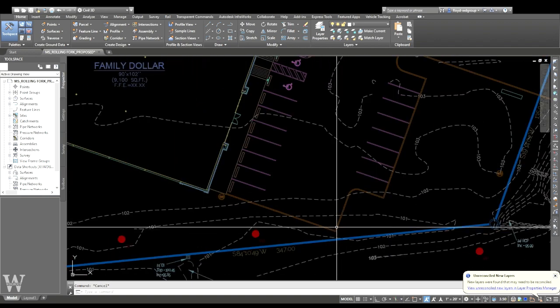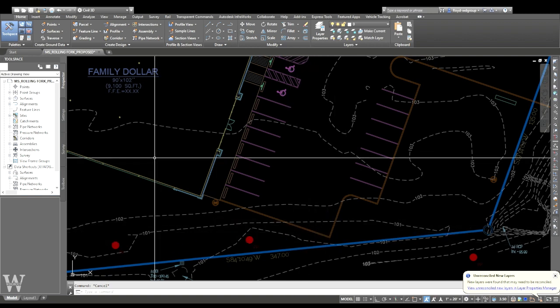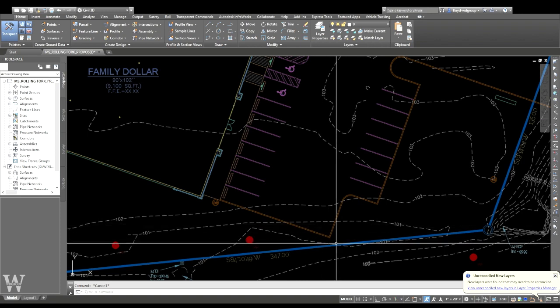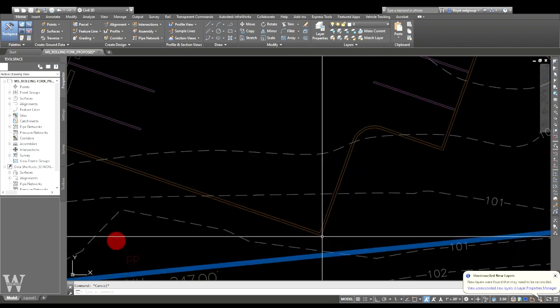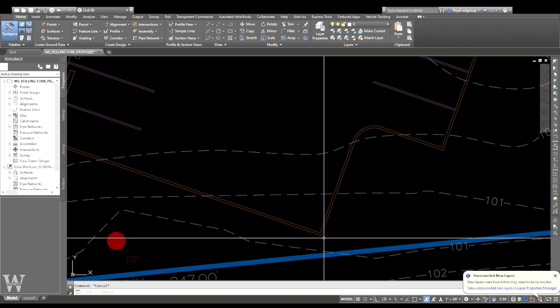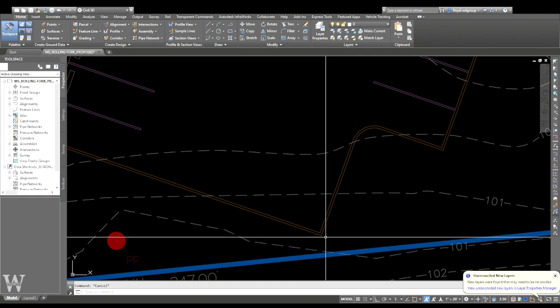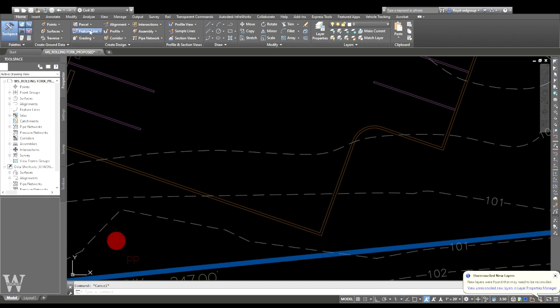So I think the first thing I want to do is figure out, okay, if I start here and go that direction, and I try to stay within, say, this is about 4 feet from right here to here. So if I go to 101 and 4 feet, I can raise a foot, right? So I could be at, that's a 3 to 1 slope, and so that would put me at 102. So I could come right here, go to feature line, create a feature line.